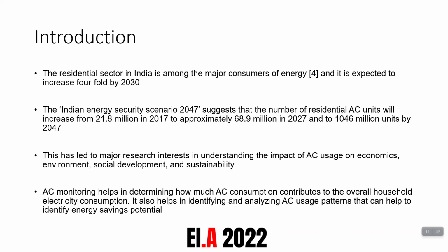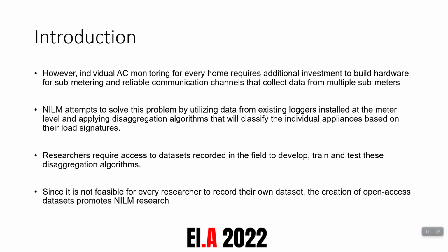However, the individual AC monitoring for each home would require additional investment in order to build the hardware for submetering, and also it requires reliable communication channels so that you can collect the data from multiple submeters and store it in the server for analysis. Therefore, the concept of NILM has come into picture. NILM, non-intrusive load monitoring, attempts to solve this problem by utilizing data from the meter level loggers, and we try to apply disaggregation algorithms that will classify the individual appliances based on the load signatures.